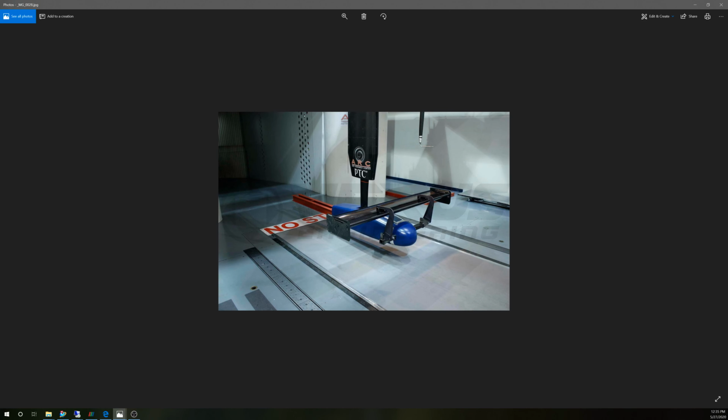Because of the wing, and there's a lot of things that go into wind tunnel data, and maybe I'll do a separate thing on that, basically you have a blockage ratio you want to keep within, and so we could actually test the full wing width in the wind tunnel, even though it's a scaled wind tunnel. So this gave us forces and moment data that we could then correlate back to our actual wing.